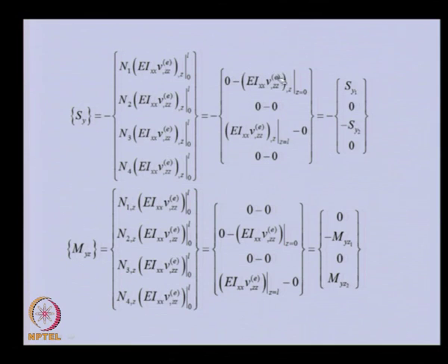This particular term is basically shear force, because here you can see a prime z, which itself represents that the term within the bracket is differentiated with respect to z. So, this is the shear force term having third degree in the translational displacement. I am expressing the negative of that term as shear force sy1. Here we will see that for z is equal to 0 and z is equal to L, n2 will be 0, so this will not contribute anything.